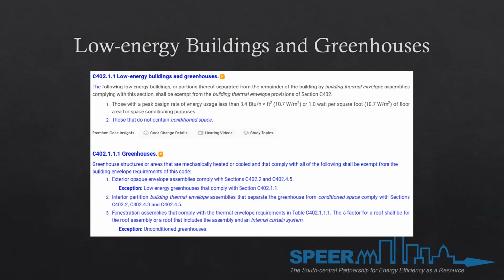I'm not trying to make their call of, does a city have the authority to say that has to be conditioned? This had big roll up overhead doors that will be rolled up. And then afterwards, they did mention to the city they were going to add a couple of window units to keep it more comfortable. Of course, that changes everything. Now it says, okay, then that's a conditioned building that now must comply with the energy code. Before, it doesn't need to comply because it's not being conditioned.